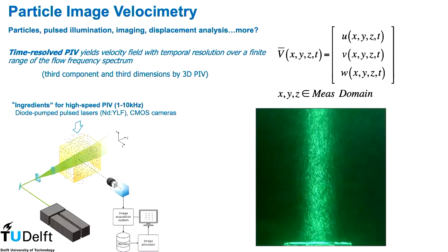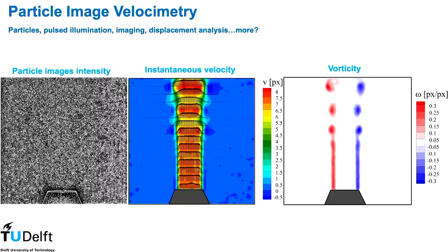And then you have a camera following these particles in time, and later on with some algorithms you track them, or you make a cross correlation. So the dream is to have the velocity vector in x, y, z, and t, such that you can even make derivatives, and then we can apply our nice methods based on gradient analysis.